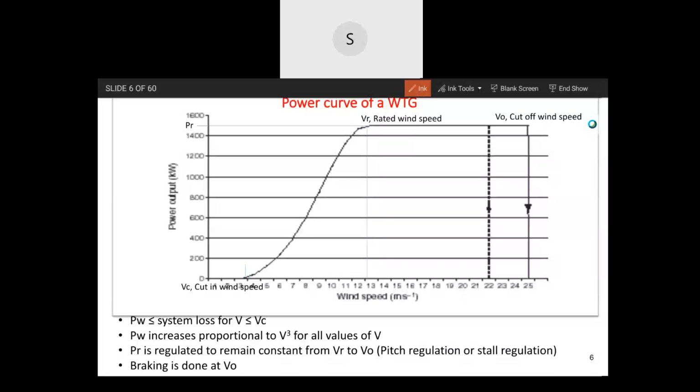That will not be there. So no power is extracted and it's not facing the wind. And after that, it is put on brake and the generator is disconnected from the grid. So for the generator, it is again safe. No power input is given, and it's disconnected from the grid also. From both sides, it is safe.